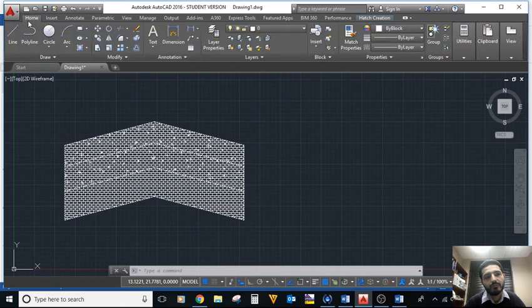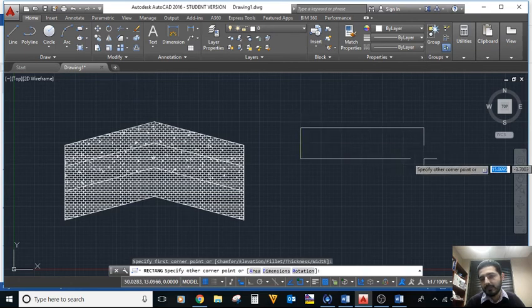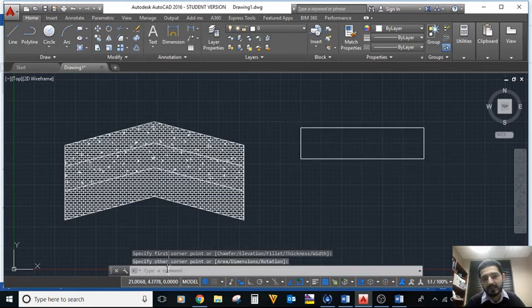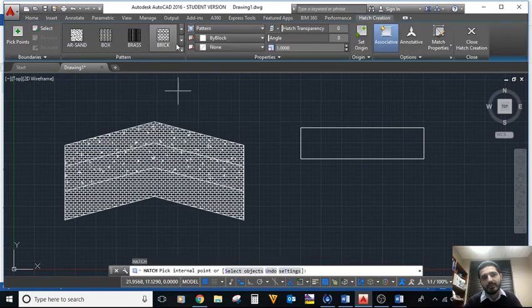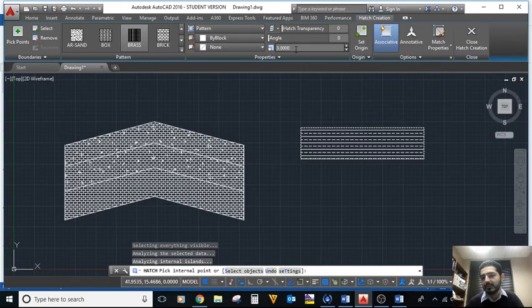So why don't we do another example here? Again, just a simple rectangle, just to make the point. Again, I'm gonna click hatch, which is just capital H. Then I'm gonna select, let's say, brass. I click here, and it's done. You can change now, this is the scale 0.5. This is too much, maybe say 3, and again it's brass. So that's how you hatch things.